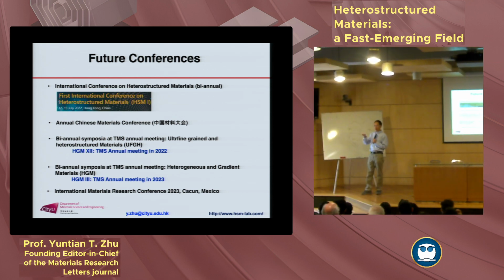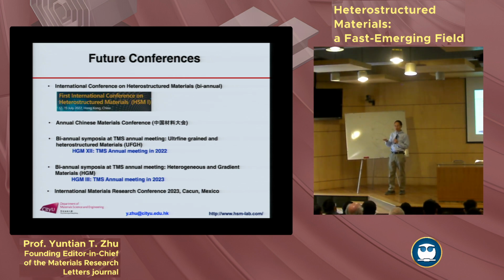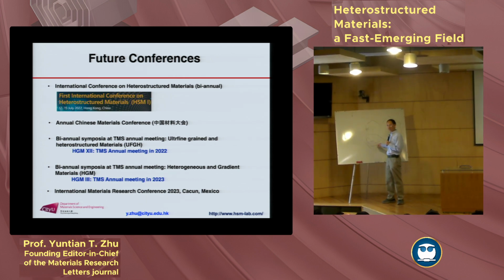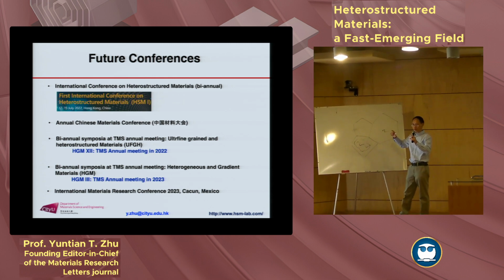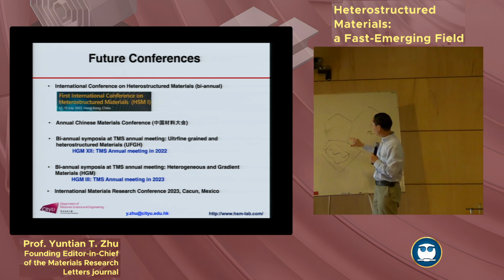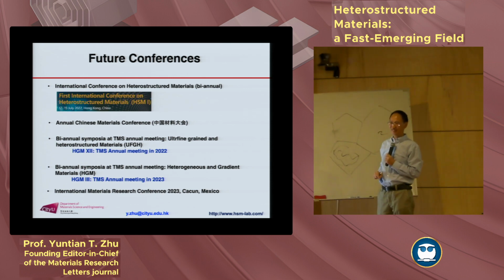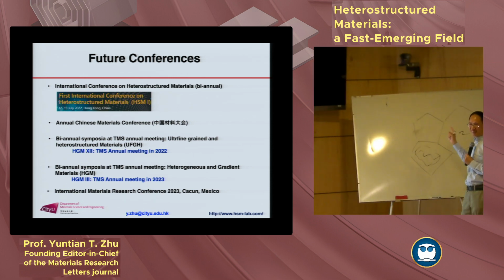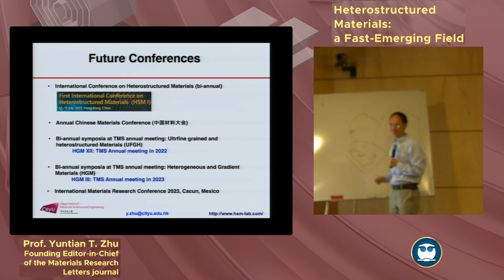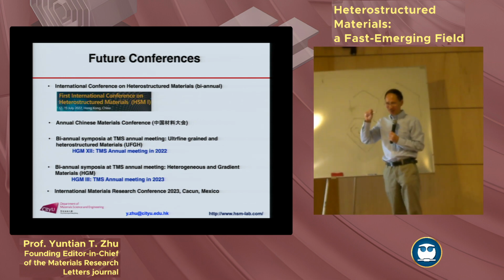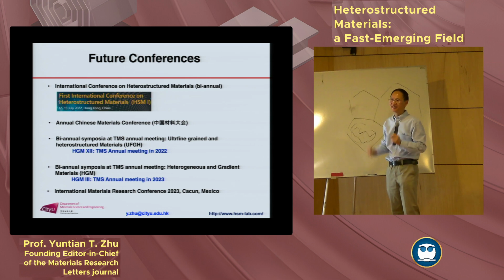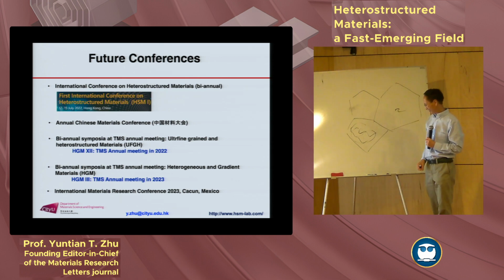When you choose a recrystallization temperature, in a short time, those with a higher dislocation density will recrystallize first. So when you see this lamellar, elongated structure with recrystallized grains, I think that's from one original bigger grain. So that's the trick for doing that partial recrystallization. You have to choose the right temperature, right time. So you have to try it. Okay? Thank you very much.